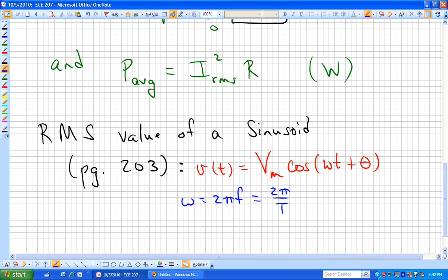You can find what capital T is, and that will give you the length of time for one complete period of that waveform. And if you wanted to sketch 2 periods to give you a feel of what's going on, then you would sketch that for 2 times capital T, and this particular relationship will allow you to find what capital T is. That's 2 pi over omega.